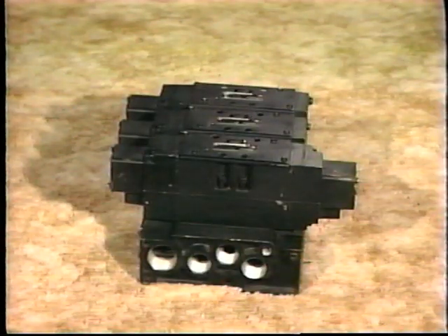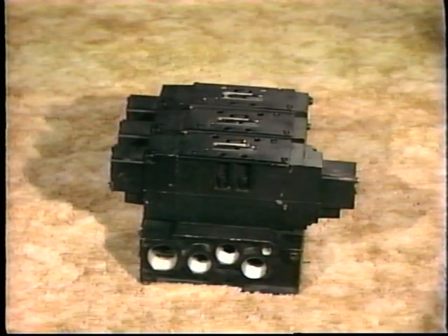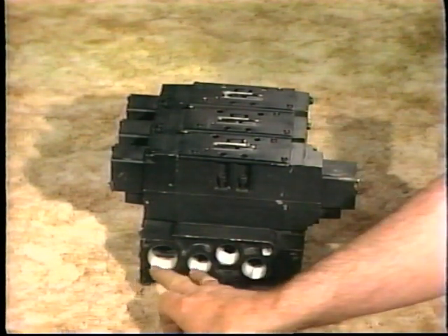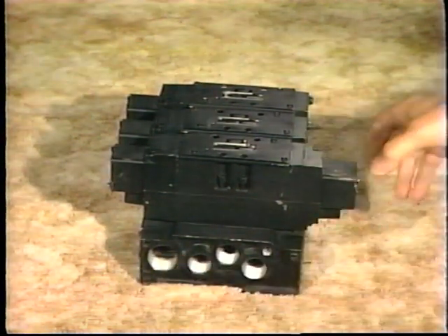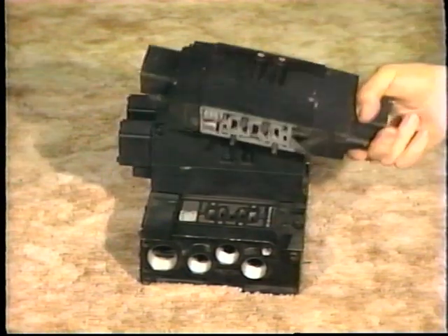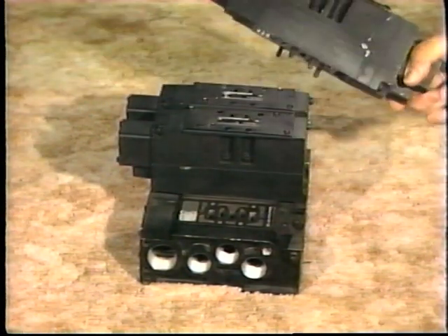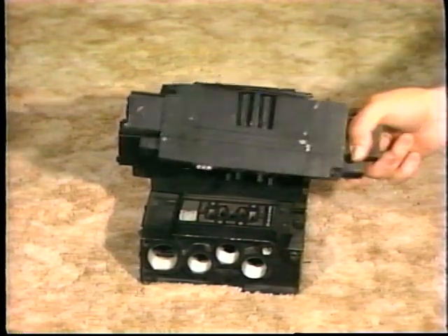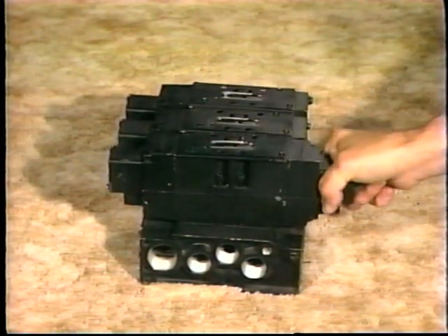For convenience, these valves are often sub-base mounted, which means the directional valves are fastened to a base to which the system piping and power is connected. As you can see, sub-base mounted valves make servicing a whole lot easier because the piping doesn't have to be disturbed in order to install or remove the valve.